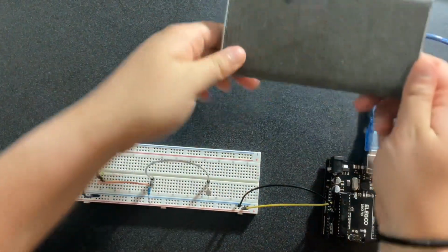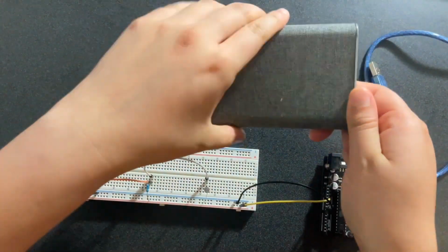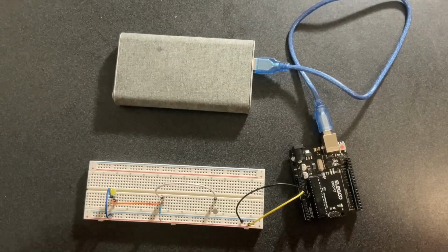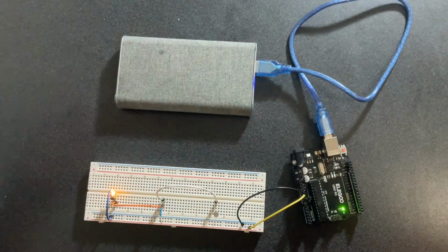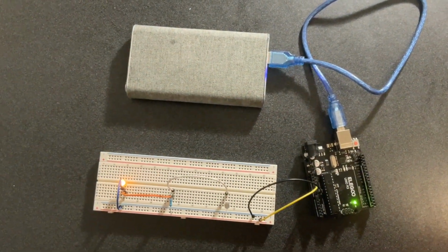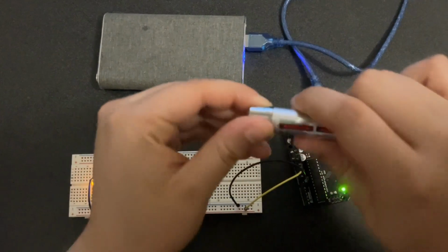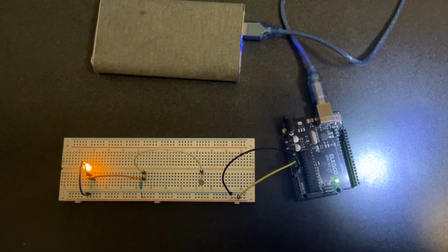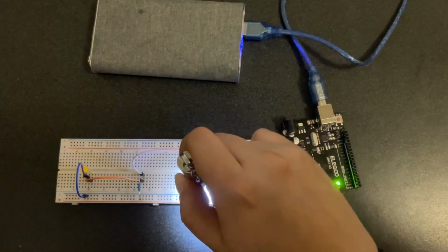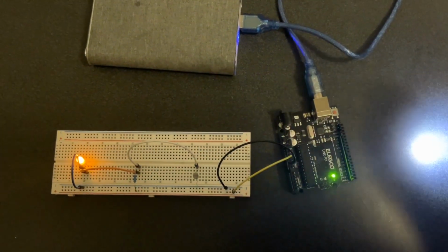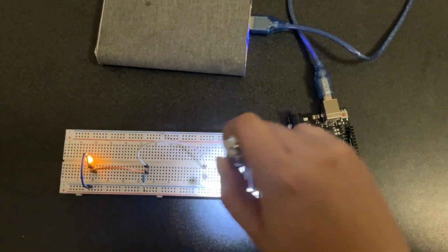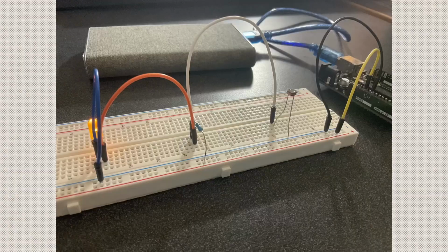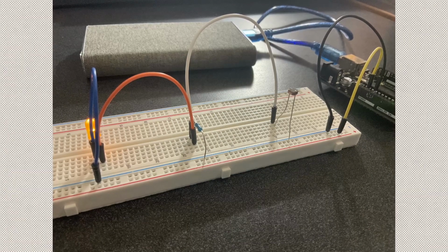Now, let's plug in our power supply. For my instance, I'm using a power bank, in which I will connect the USB cable into. Great, so now let's bring our project to life by powering on our power bank. As you can see, the light turns on automatically. Now for the real test. By using a small keychain flashlight, I'm going to go ahead and move over the LDR with this light to see if the LED light turns off. Wonderful! Now we know that the LED light and the LDR sensor work, completing the final series circuit.